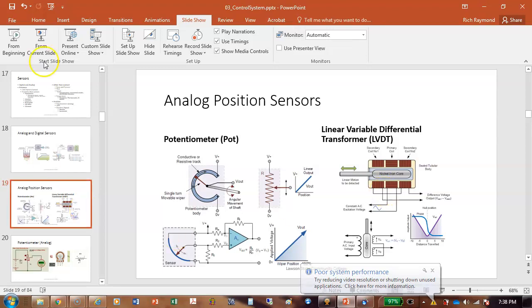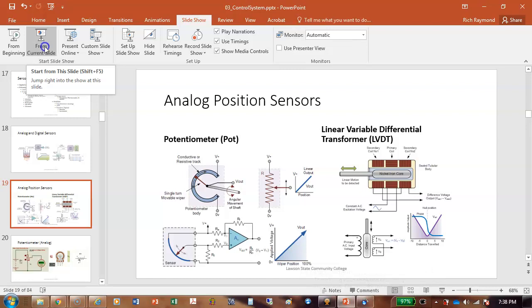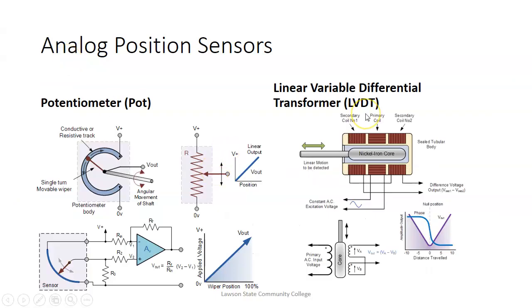If you looked at them, they look a lot like a shock absorber on a car. If y'all have ever seen a shock absorber on a car, they look like that. We seal them up really nice. We run into a lot of these on hydraulic systems. They're very, very rugged. What we do is we get a differential voltage depending on where the core's at.